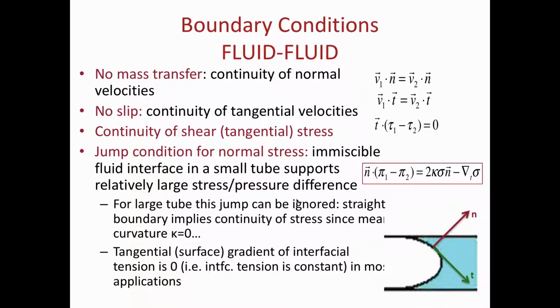Dr. Brown, just to make sure, that equation relates the pressure difference to the curvature of the fluid interface. Right, so pressure is built into my molecular stress tensor. I have a pressure plus shear stresses. So the difference between the two is related to the curvature of the interface. Basically, the interface curves in order to support that jump. That's why it's curved. It curves to balance things out at that interface.